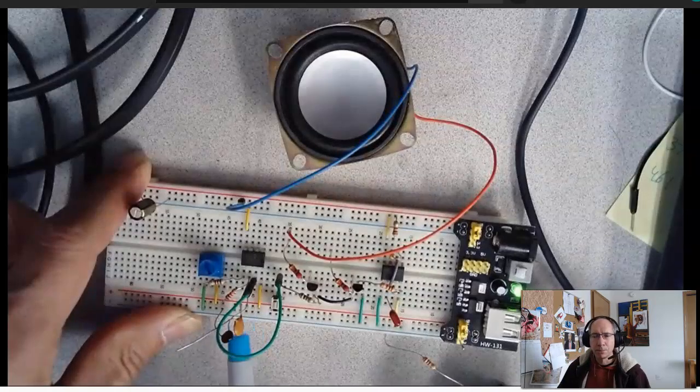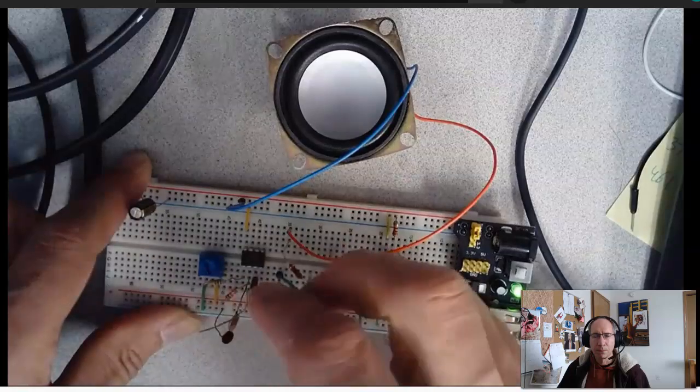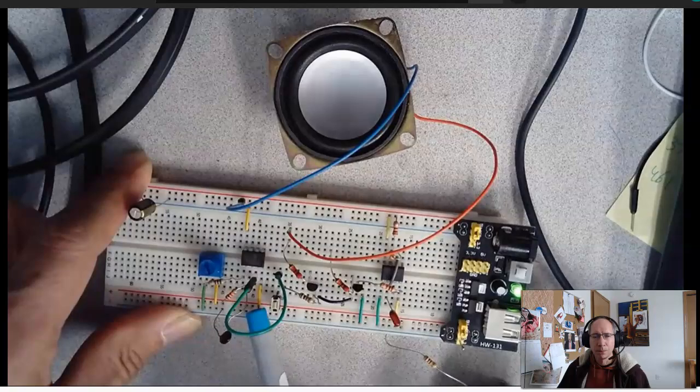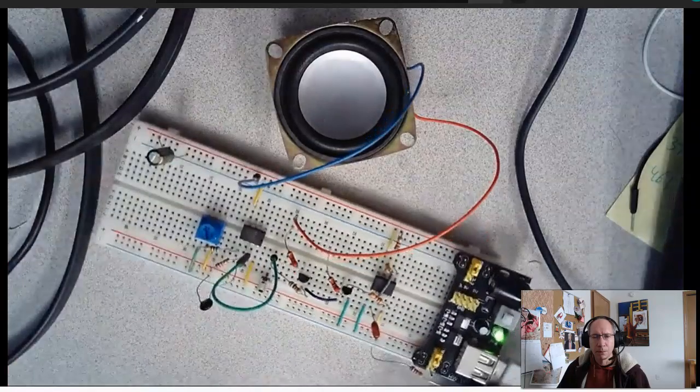The comparator is this guy. Here's the thermistor, and the voltage divider. When that goes above the B minus, which is set to 4 volts, the speaker turns on. So when it gets hot,